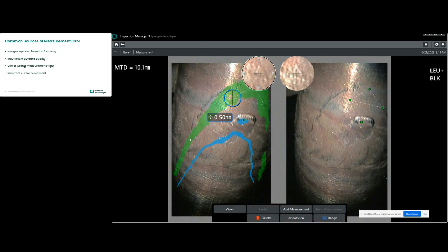And the first thing you'll probably notice is some colored banding here on the surface. So the green masked areas are showing points on the surface that are lying very close to the reference plane that was established by these first 3 cursors. The areas in blue are points on the surface that are very close to this 0.5 millimeters above that reference plane.